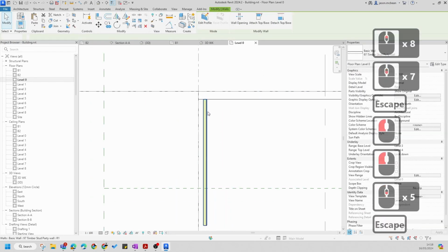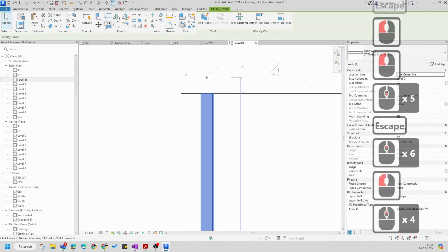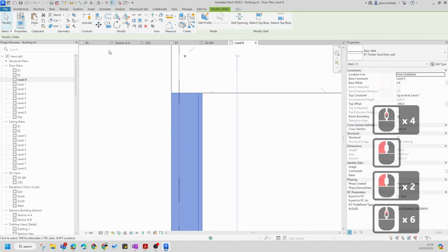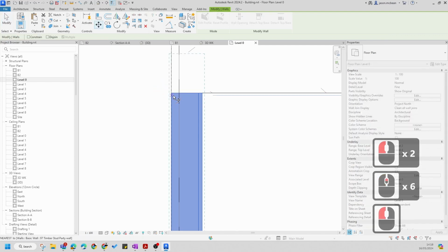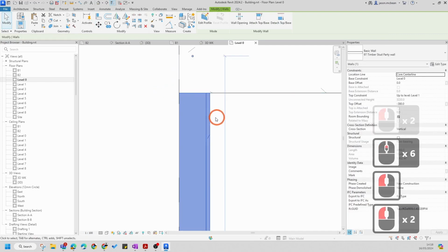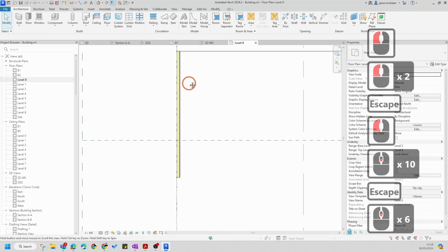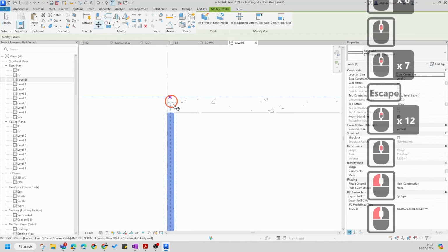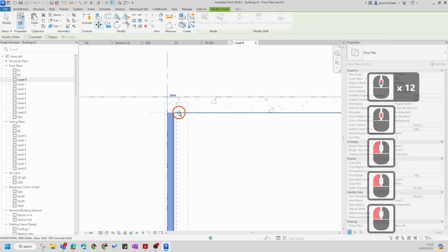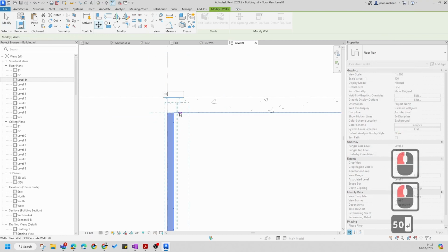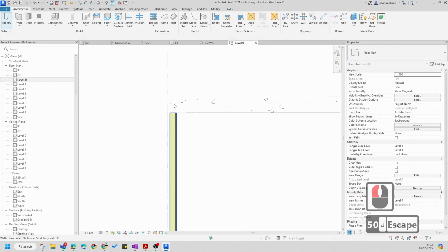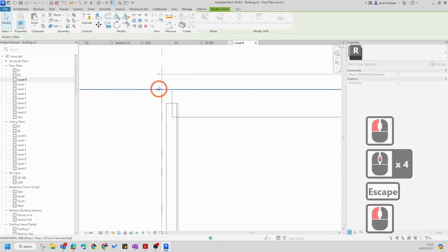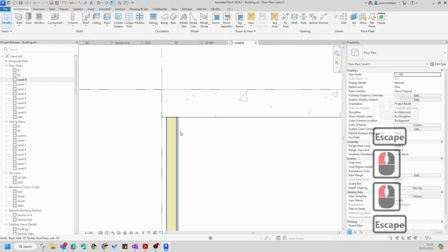Okay, I'm going to stop it there. So technically my party wall, if I move this, I can put the timber stud right against there. My apologies, move it back. Or you can give it a cavity. So timber could sit right against that, so that becomes my party wall. Or what I might do is just move this away a bit, by 50 mil. Then you start getting that arrangement. Now because these walls are joined, they start working together, so let's just remove that function.